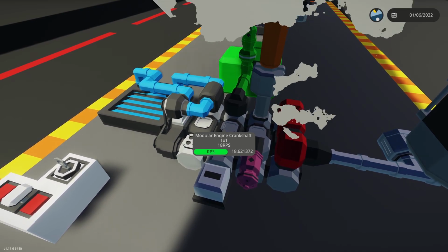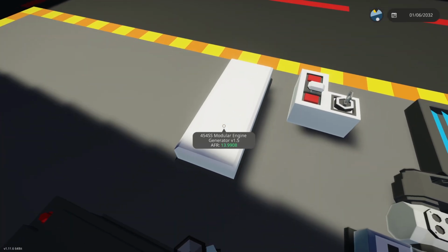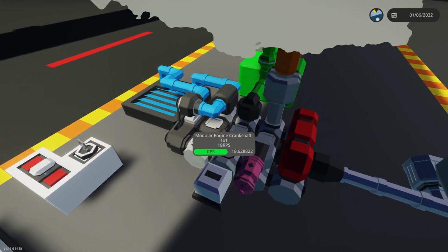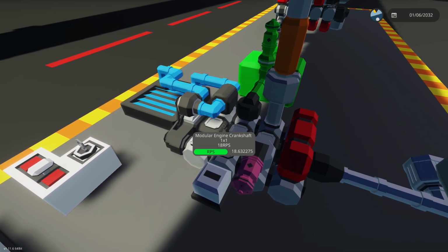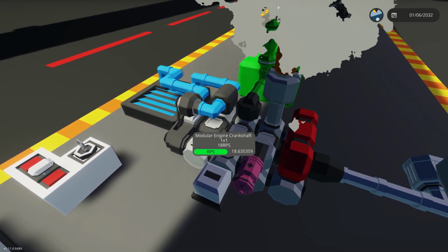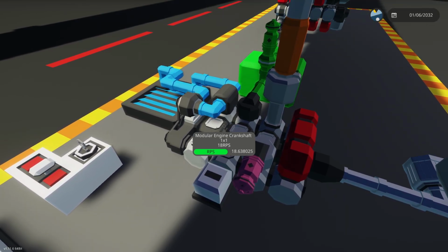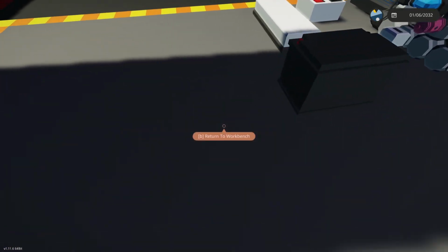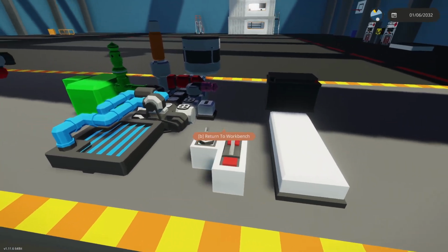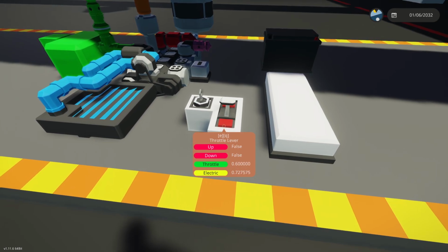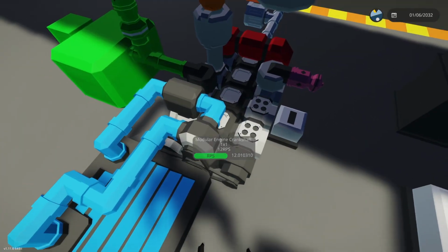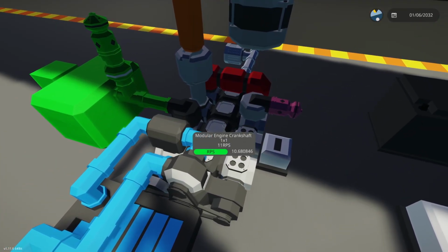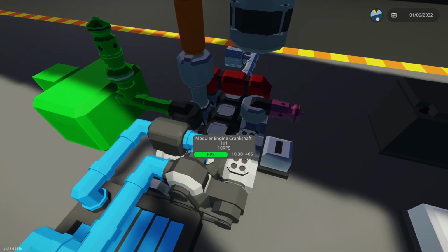Now 30 is the maximum cutoff I set in my microcontroller, because I find anything over 30 is just going to cause your engine to overheat way too quickly. So I've limited that, otherwise a lot of people are going to be saying your engines are overheating or whatever. So this seems to be a happy medium for this engine at 100% throttle. Obviously, we can throttle down, and it's going to find out and balance itself at a lower level, obviously less output. Hopefully it doesn't stall out.